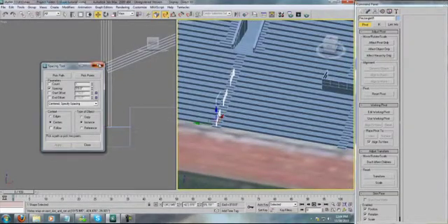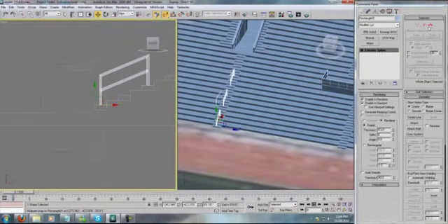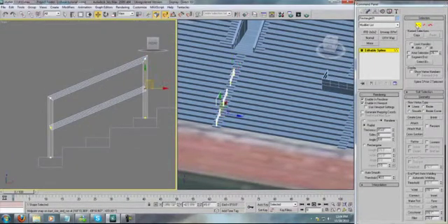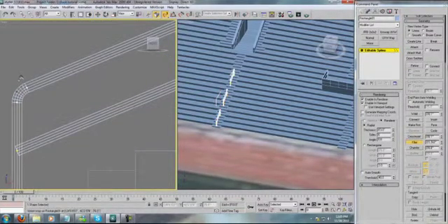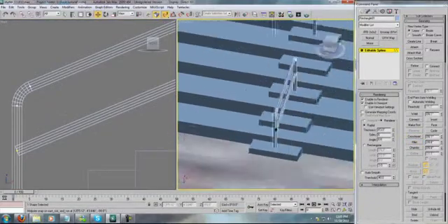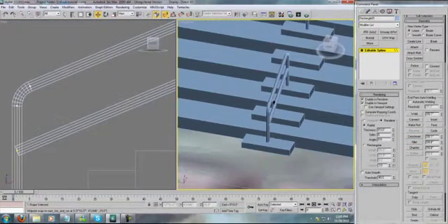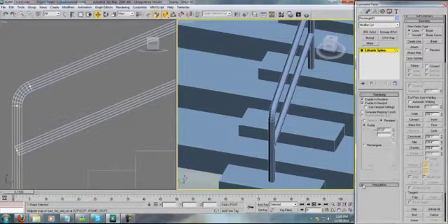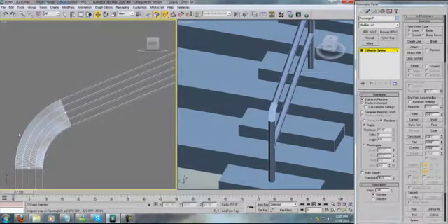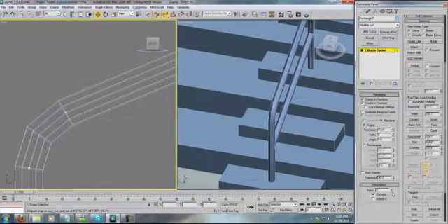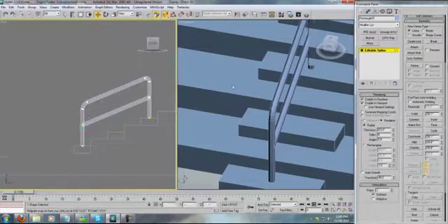The second useful aspect of the spacing tool, I'm just going to grab the leg off one of these. Oh, just to illustrate the point of instancing, say we want to make these rounded edges. Let's go up here and hit a fillet on this guy, and fillet the corner. Now, all of them that's been applied to, even the one that's not selected. Since we really want uniformity, that's really important. There's way too many polys in here, so let's go to interpolation and bring that down. That's going to increase or decrease the amount of spaces we have when we do something on a Bezier curve. I think just taking it to 1 or 2 steps is going to be just fine for our purposes.